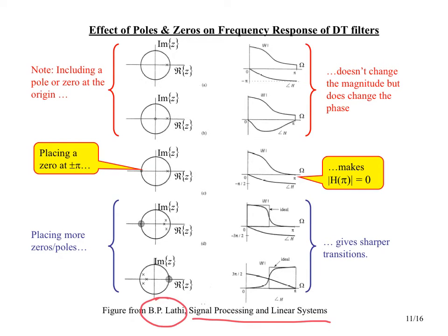The magnitude has even symmetry. The phase plots have odd symmetry. So we start off up at the top here. We've got a single pole, and it's on the real z-axis. So that's going to cause the frequency response to be pushed up around an angle of 0. And remember, angle of 0 is frequency of 0. So we get a little push up at frequencies near 0.